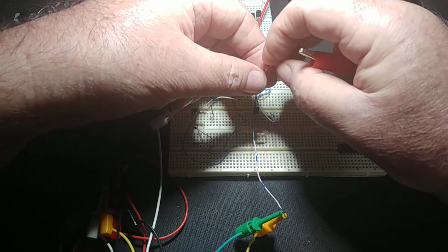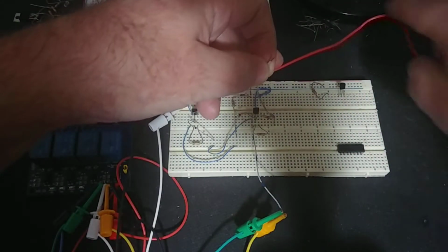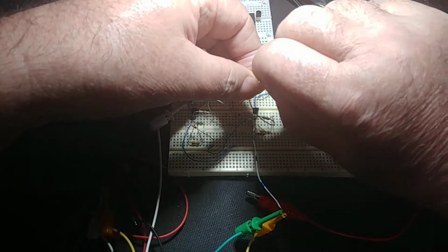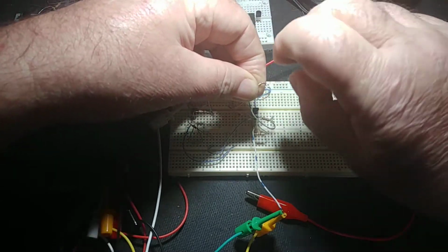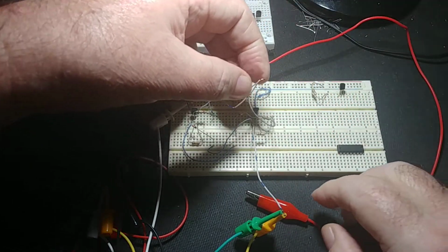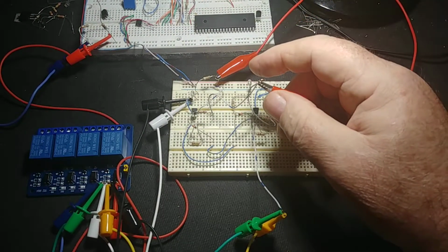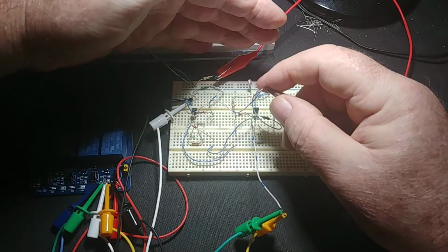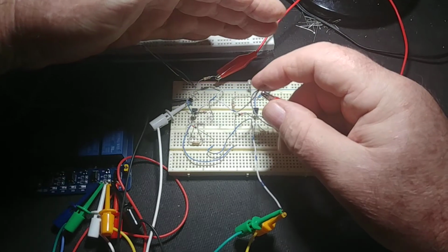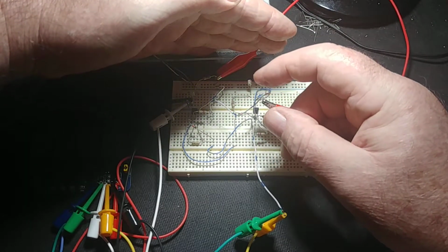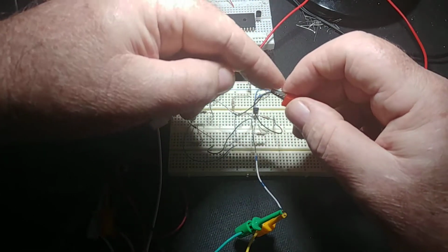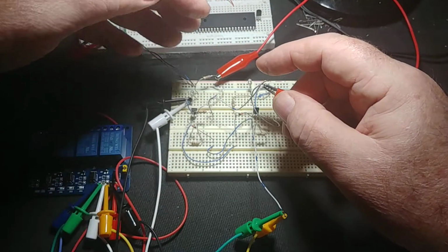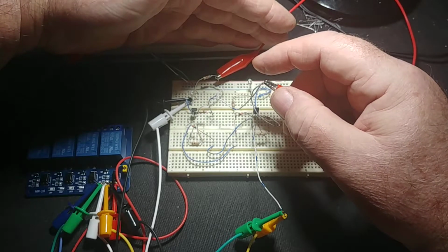So if I put these two inputs together, that's my touch light going off. So if I twist these inputs together, so that's like one wire. So if I touch this, you see the green one came on. The blue one came on. Whichever one comes on first will shut the other one off. Now, whenever you touch a wire with anything, you get multiple bounces. So that's why you've seen it switch between blue or green, and it was like oscillating. It's not going to do that with a microcontroller.